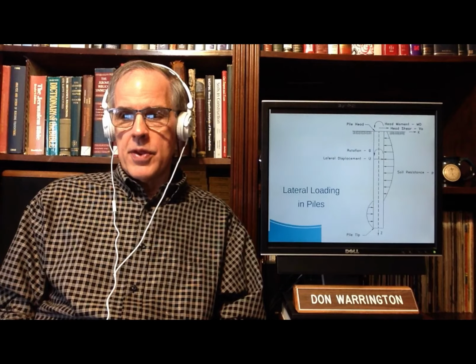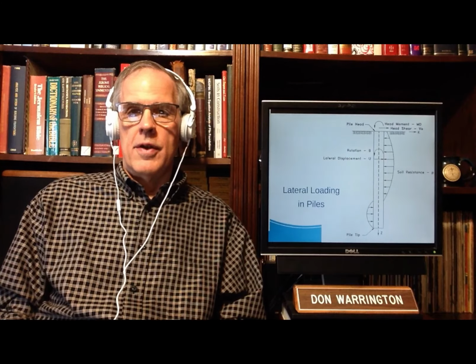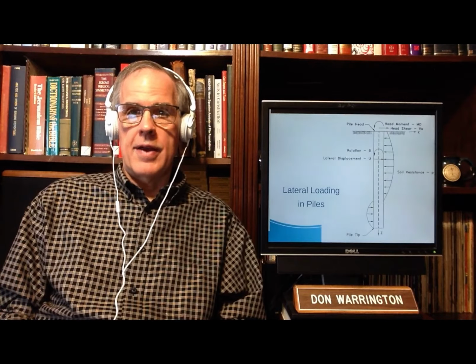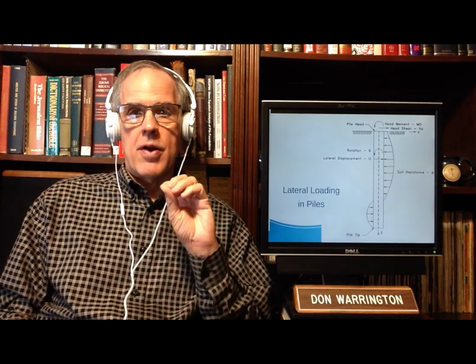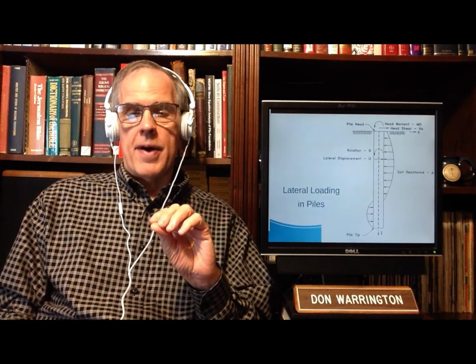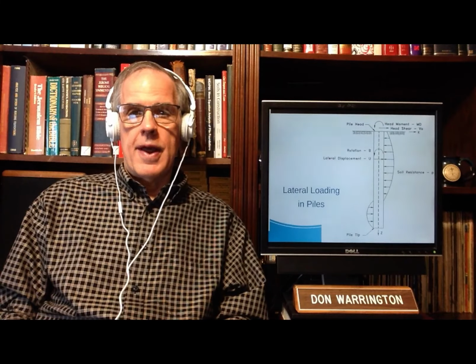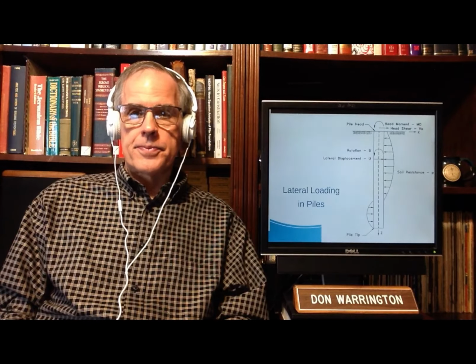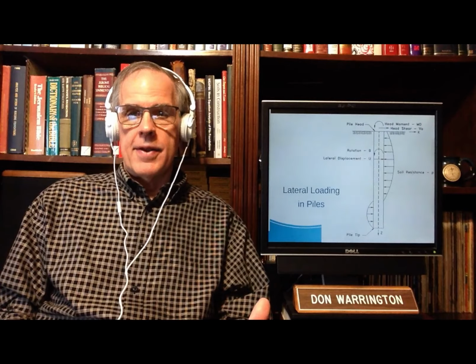And basically, those loads at the pile head can either be horizontal or a mixture, actually. You can have both lateral and axial loads at the same time, but let's stick with the lateral. If we're sticking with lateral, we're talking about a horizontal load on a pile head. And also, the pile can have a head moment. We're going to talk about how that's generated in a little bit. And then, as you go down, any beam reacts as beams do in bending.